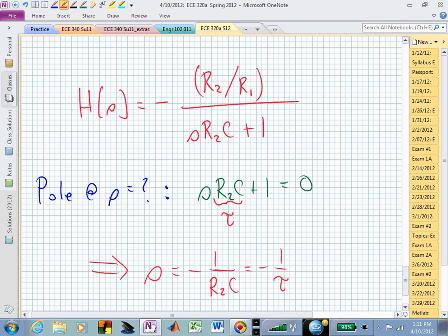So if somebody said, I want my low-pass filter to have a bandwidth of 2 radians per second, maybe you've already picked R2, or maybe you have to live with what Josie has in the stockroom. And capacitors are probably more precious than resistors in terms of finding one, so you're stuck with a capacitor. And the homework, what was it, 4.7 microfarads that you had to live with?